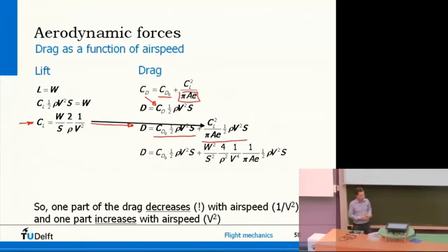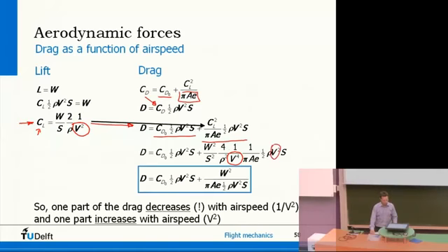So squared, I get airspeed to the power 4, and I have to multiply that with half rho V squared S. So these V squareds, you can get rid of two of them, and this is the final equation you get. It's a very simple derivation. You just fill in the parabolic lift-drag polar in the lift and drag relations. But this is what you end up with.